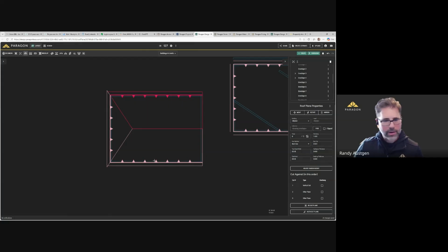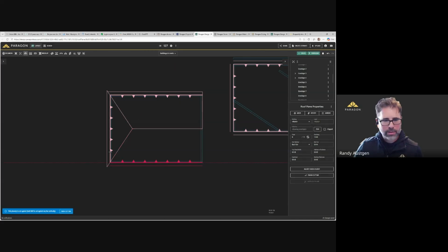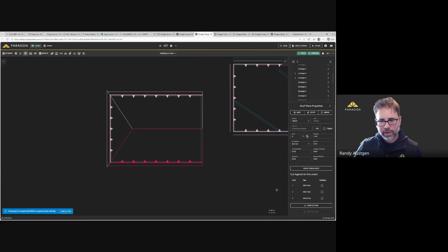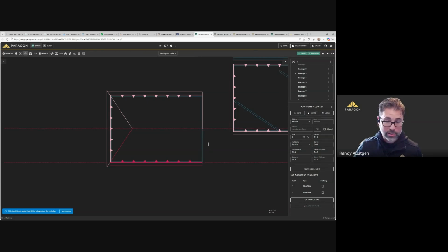This is a very minor thing, but it may help you avoid some frustration when you are cutting planes here. I'm going to do this again. And when you go to finish, I don't know if you all saw that. If I add another, oh, here's a huge tip: Control Z is going to get you out of the last selected plane cut, if you will.